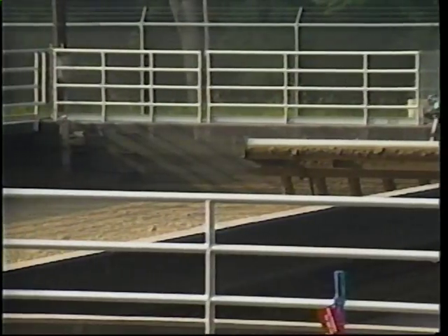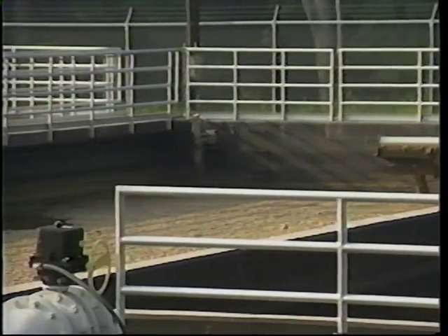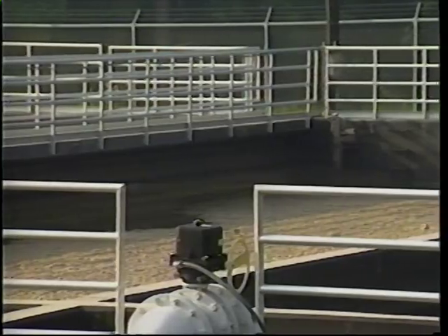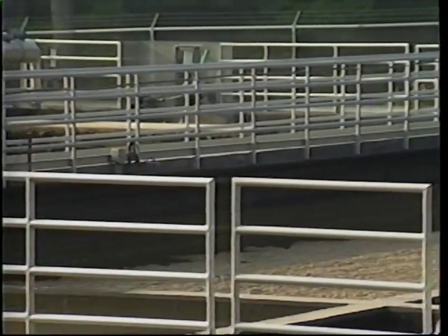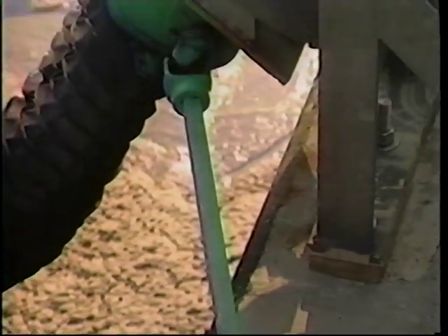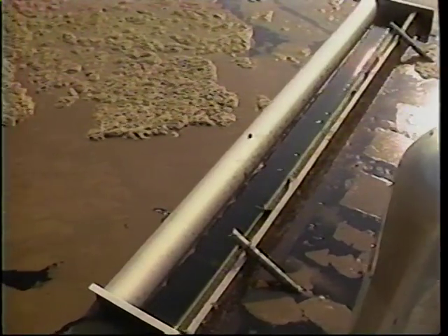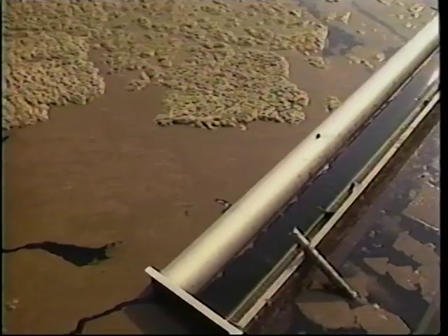The settling mode, where the tank essentially becomes a clarifier. No mixing, aeration, or filling takes place. The decanting mode, where some type of decanting device lowers into the tank and removes the treated wastewater from the aeration tank. Usually sludge is wasted from the tank in this mode as well.